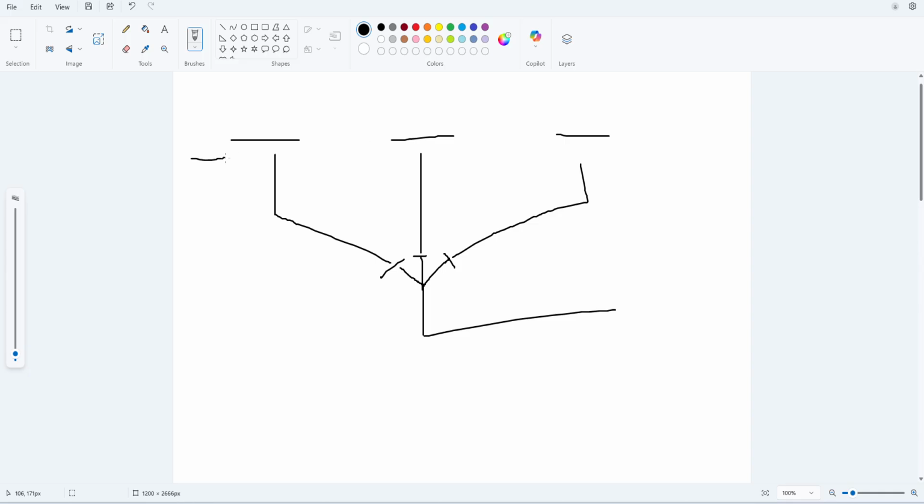If we look from this side, let's say you have a wall here, and this pipe is all in one line. Let's say it goes this way, and then we can do it like this, a P trap, and then it goes to the sink.